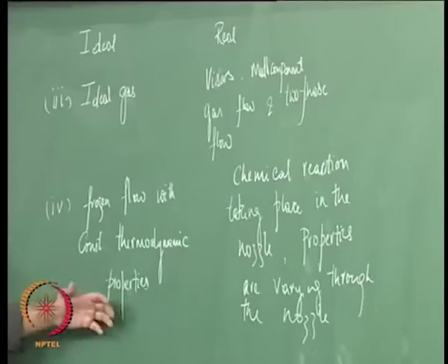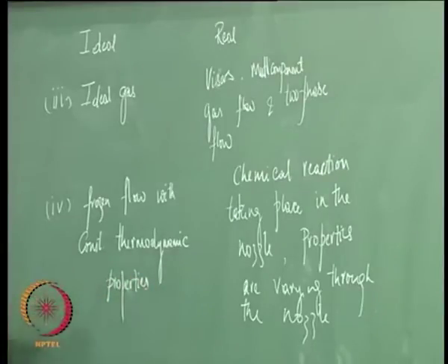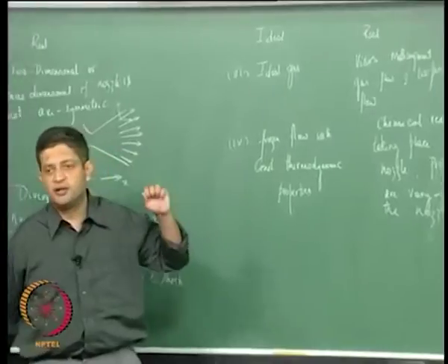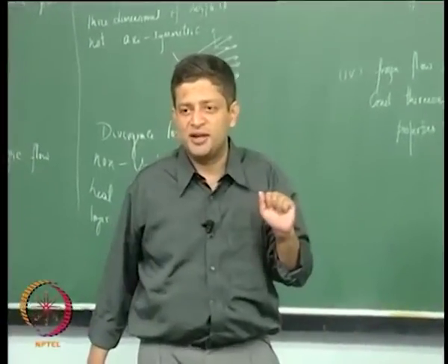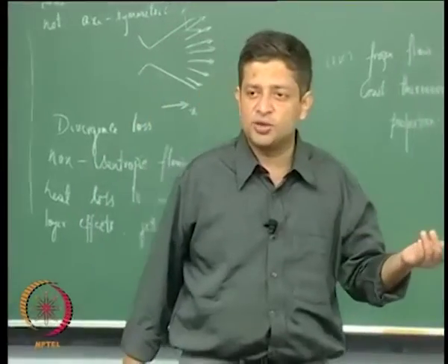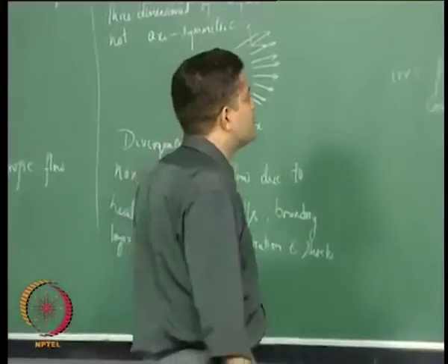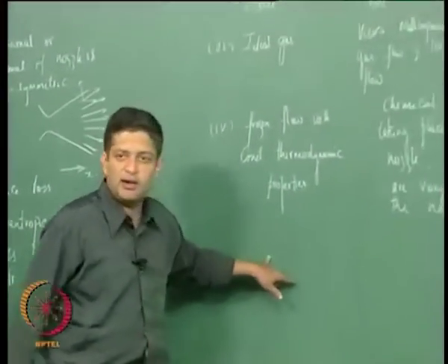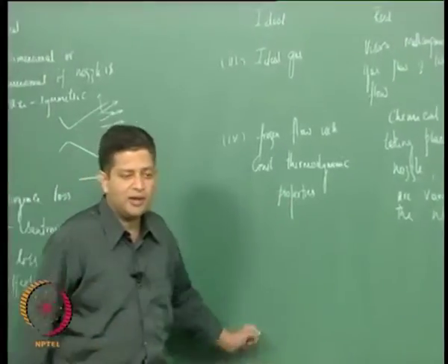All of them were a negative contribution. This is going to contribute positively, primarily because if you look at what is happening inside the nozzle, the pressure and temperature are decreasing. So, that will favor exothermic reactions, and therefore, you will get a slightly improved performance than what we had calculated. So, we will look at it in a little more detail in this class.